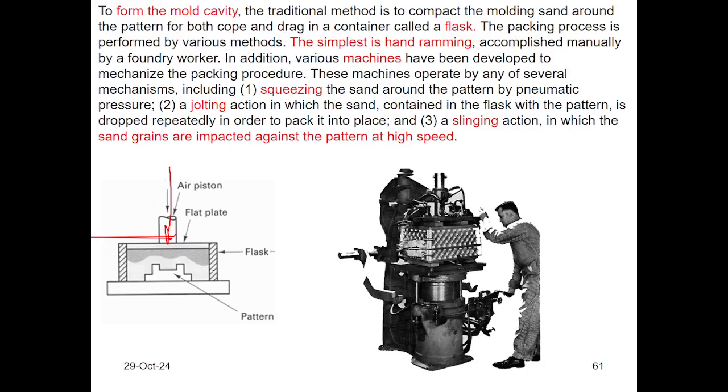But if the size of the mold is greater than a threshold value, then we use a mechanism, a pneumatic or hydraulic system, to run the piston against the pattern. Using a piston mechanism, we can apply the necessary force to squeeze the sand particles.